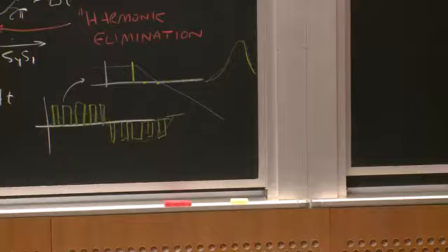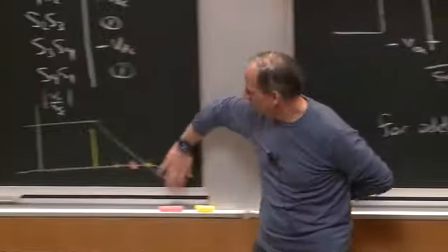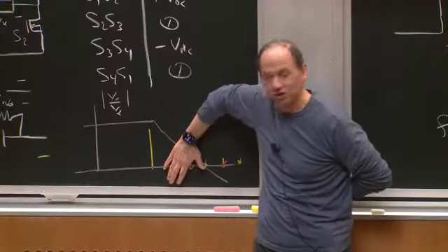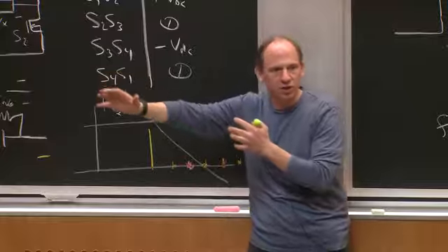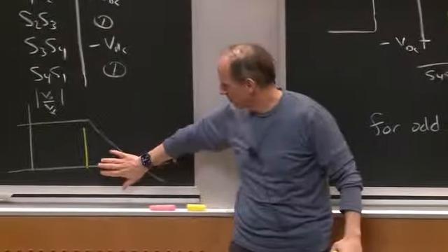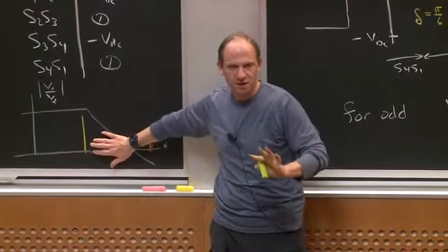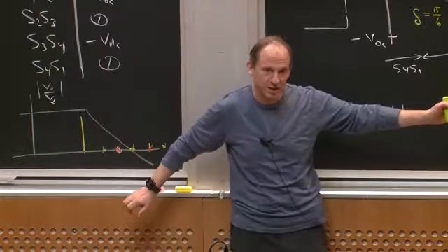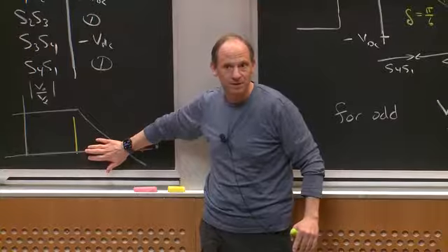The thing about that is if I think about a low pass filter, it's easy for me to kill the high frequencies in a cutoff. It's hard for me to eliminate stuff that's near cutoff. So I'm making the challenge of basically pushing the frequency content up and keeping the stuff that's hard to filter low. Okay, so I'm not getting rid of high frequency content, I'm actually increasing it. But what I am doing is getting rid of the stuff that's hardest to filter. Okay, any questions about that?